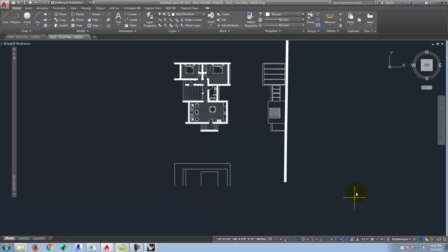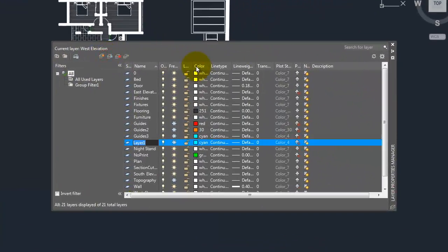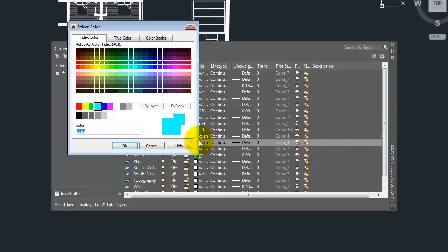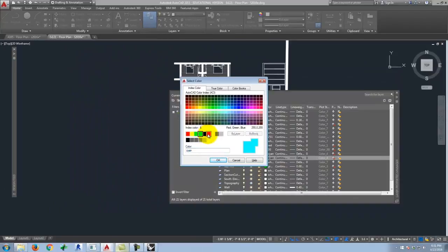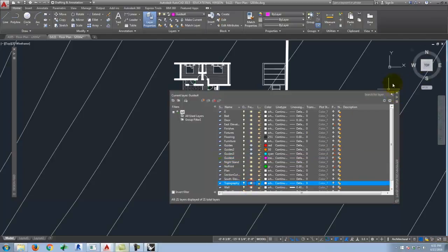Now I need the topos for this. So I'm going to create a brand new guides layer. And we'll call this guides 4. So you see that I don't hesitate when I'm creating guides, right? Lots of layers helps your organization. So we'll do guides 4. It's again a non-printing layer, and we'll make it active. And I also need to turn on the topography.